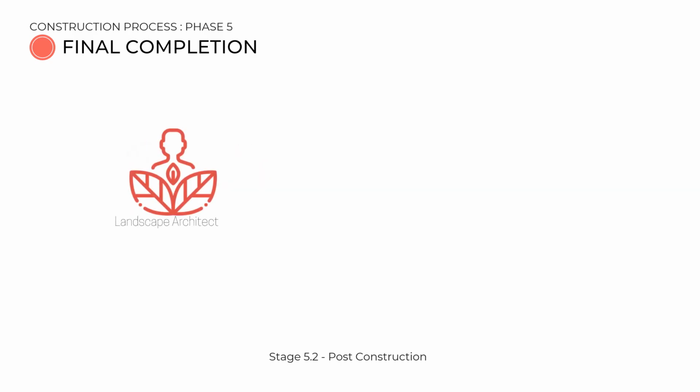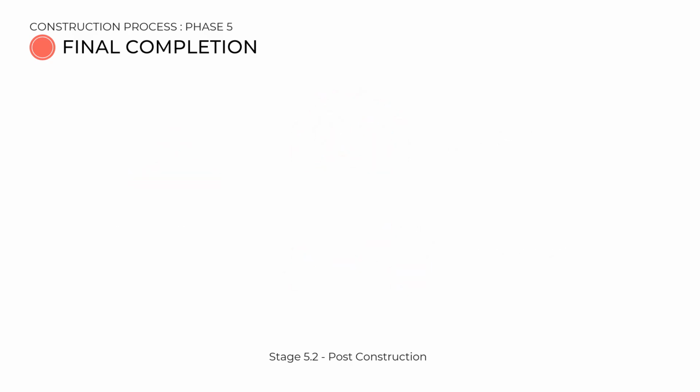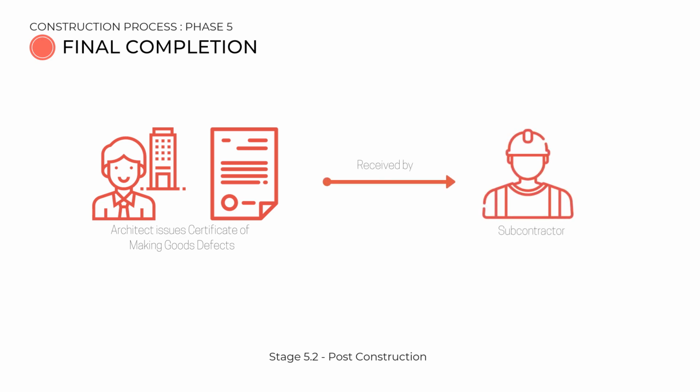The landscape architect ensures that softscapes are well maintained and defects are made good and replaced. The architect then issues the certificate of making good defects to the subcontractors after defects are rectified. This signifies that all works are officially completed.